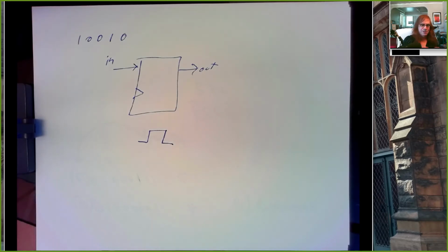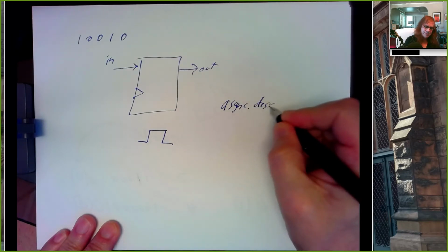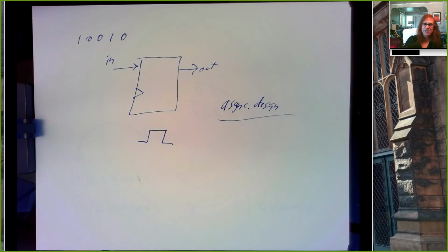And that's a really different kind of circuit. There's a whole discipline called asynchronous design that basically deals with that kind of approach to engineering. It's fabulously difficult to design and debug circuits when you don't have a clock like this. But the payoff is potentially huge. Potentially things work a lot faster and at a lot lower power. But without the clocking to move everything one step at a time, it's worlds harder to do. So this one is synchronous.